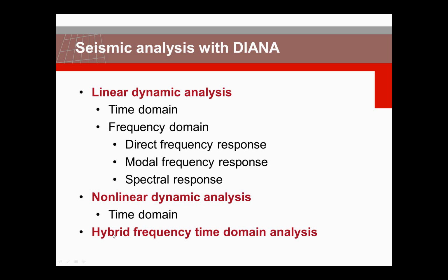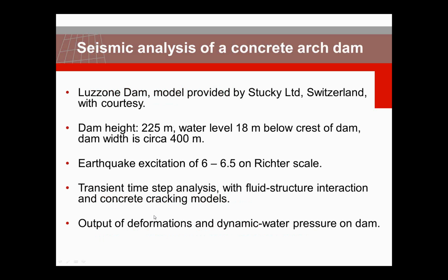Very recently we have developed a new analysis procedure, which is hybrid frequency-time domain, in which we can combine both aspects, the advantages of frequency analysis and nonlinear analysis. So for example, the compressibility of the fluid in a dynamic analysis or the bottom absorption in combination with nonlinear failure behavior of the concrete. But in this case study, we will do a transient analysis of a concrete arch dam.